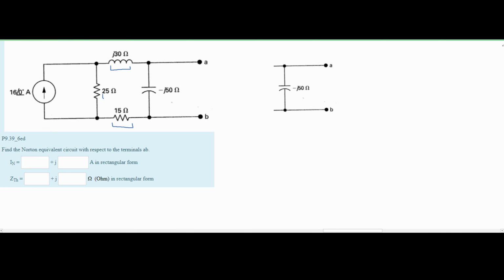And then once we move this, because we know that we are going to have this resistor here, and then our inductance and our resistor here, this is also going to be in series. So we're going to add our 25 to it. So from this, we are going to have a resistor right here, and for this resistor, it's going to be 40 plus j times 30, and that's because we add all the impedance together.